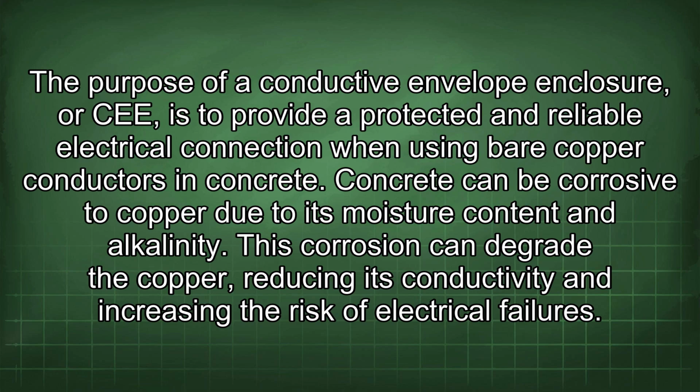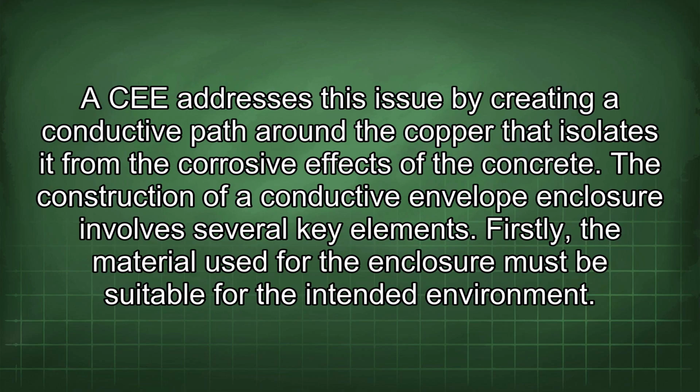The purpose of a conductive envelope enclosure, or CEE, is to provide a protected and reliable electrical connection when using bare copper conductors in concrete. Concrete can be corrosive to copper due to its moisture content and alkalinity. This corrosion can degrade the copper, reducing its conductivity and increasing the risk of electrical failures. A CEE addresses this issue by creating a conductive path around the copper that isolates it from the corrosive effects